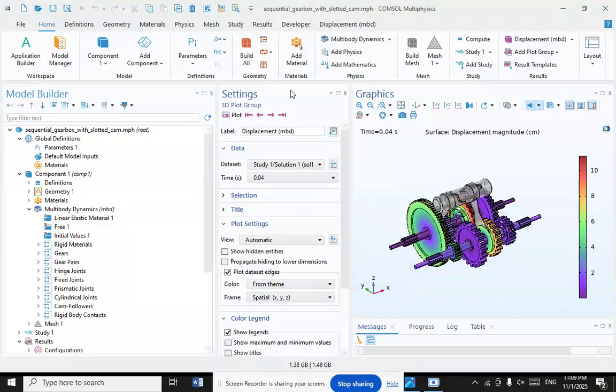Most FR (front engine, rear-wheel drive) vehicles have a transmission that sits between the driver and the front passenger seat. Floor-mounted shifters are often connected directly to the transmission, while front engine vehicles with rear mounted gearbox, or rear engine or rear wheel drive vehicles, often require a mechanical linkage to connect the shifter to the transmission. Column mounted shifter.